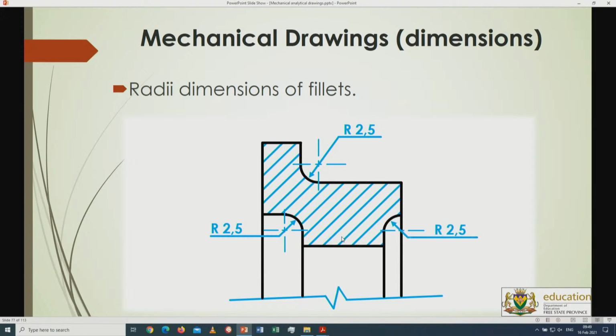Right, then also radius dimensions. You will add it like this. You will add a line going through the center. So in other words, that arrow is touching the specific object, the circle or the radius, in this case. It's going through the center of that circle, downwards, and then from there outwards to build a platform in order to write radius 2, because there's not enough space inside here, so you can go outside there. And the same with this one, and the same with that one over there, always going through the center point.